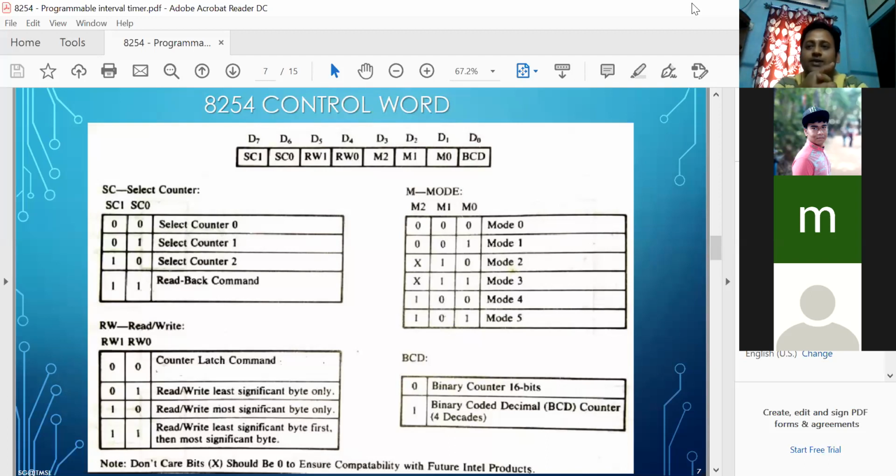There are several software ways and different hardware methods implemented to avoid the bouncing problem. What is the use of the software method? You perform a delay of the time when the signal is bouncing.